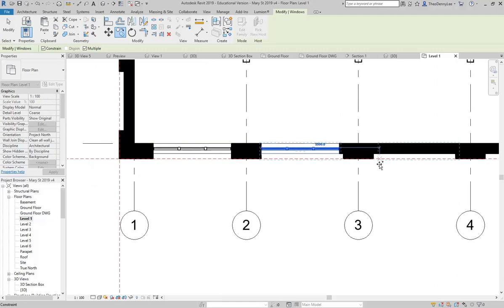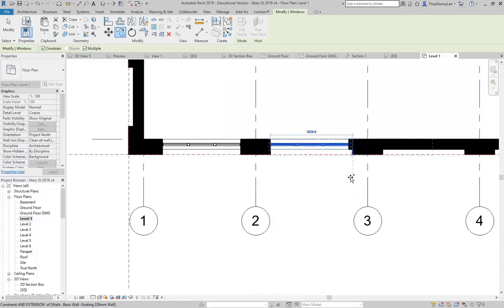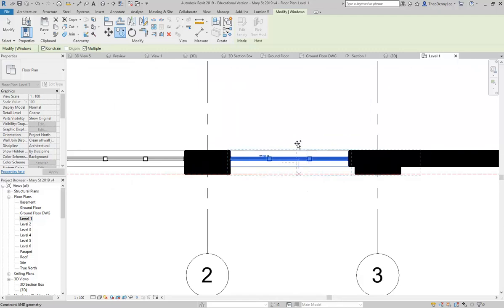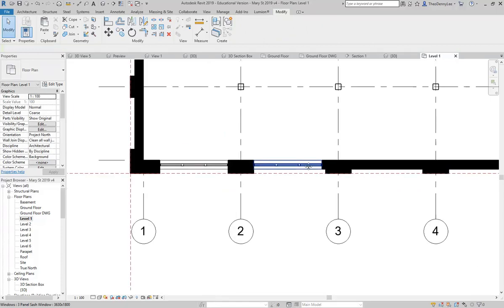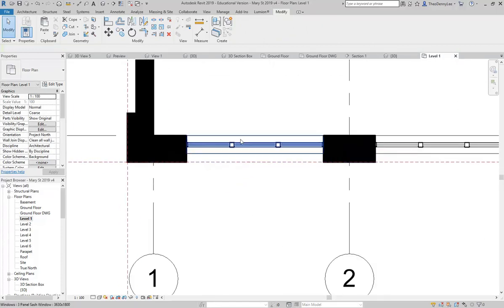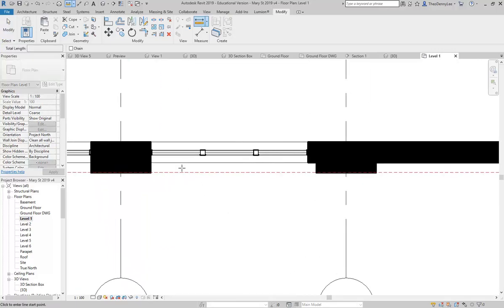And then you just go along to each one. But see how now it's not quite right. So the second one, you can see there, I'm going to pause there and then press escape. Right, because this one's bigger. So that shows you what can happen even with equal grid sizes, you will get different opening sizes. That's just the nature of geometry. So, I'll measure from this corner to this corner, and I think you're right, it's 3820.